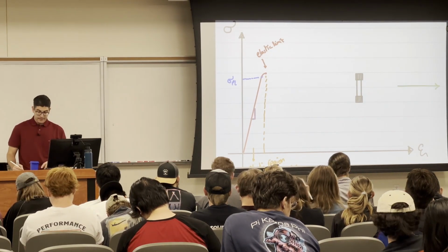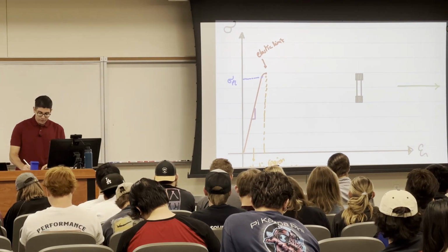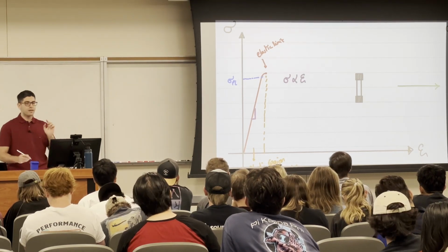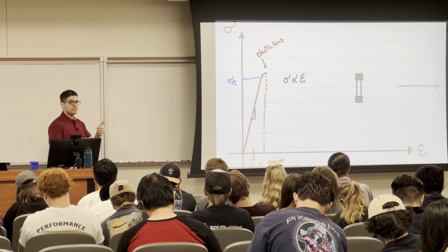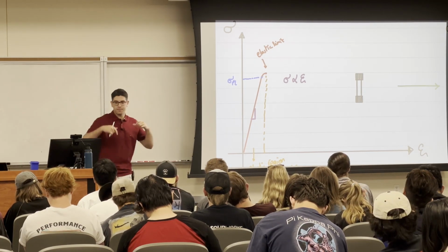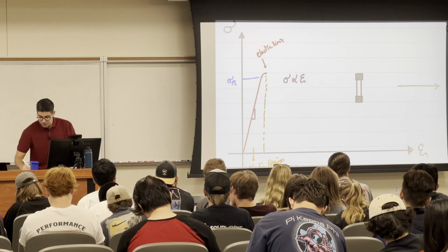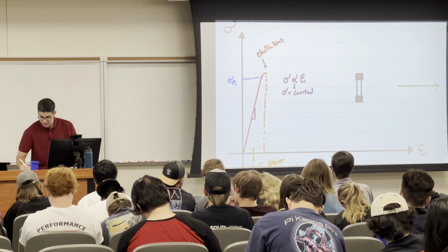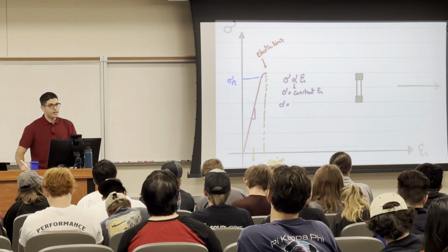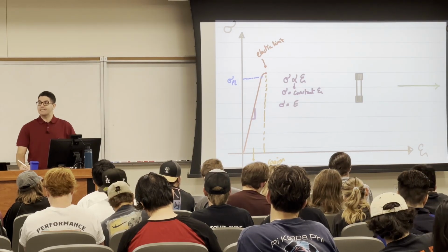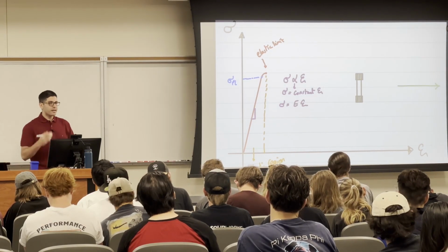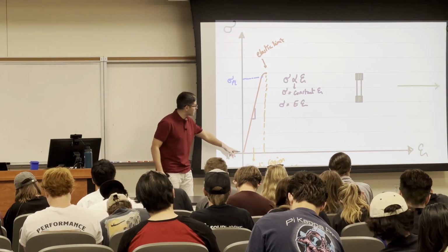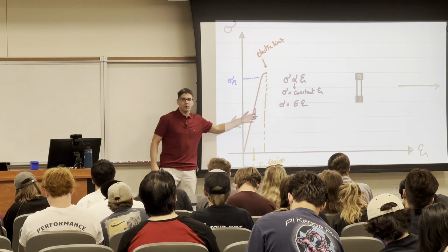Okay? And if you want to figure out this slope, first you all agree with me that the stress is proportional to strain, which means if I increase the stress, the strain is going to increase, and vice versa. So we can remove this proportion and say there is a constant here. And this constant, ladies and gentlemen, is called the modulus of elasticity, which we explained before. So every material has its own modulus of elasticity, its own curve or relationship.